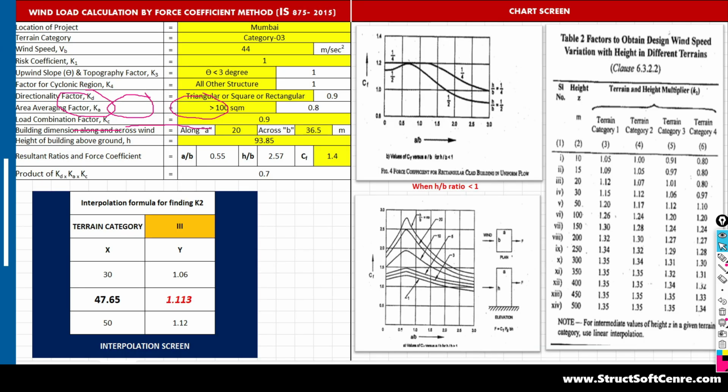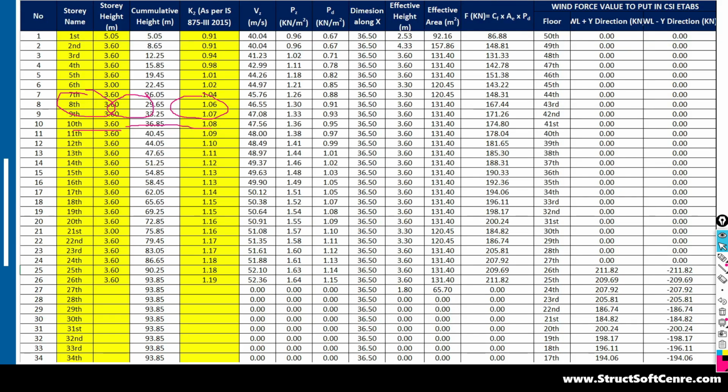Then when your structure is going to be subjected to wind loading, and it is supposed to be a tall structure, 20 floor, 30 floor, 40 floor, whatever the number of floors are there, based on that we have to do the calculation for the wind load with the help of the spreadsheet. So how to do the calculation for the wind load, that we are going to study basically from the reference of IS 875 part 3, doing that calculation by the Excel sheet, and then we are going to implement it in the ETABS software.